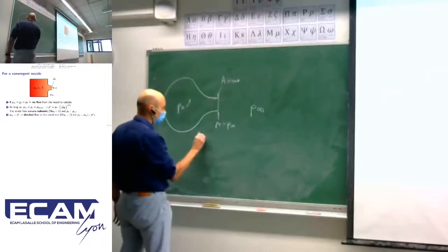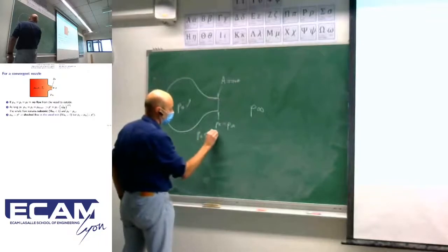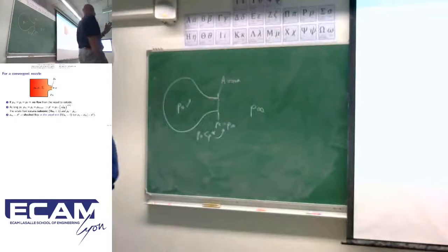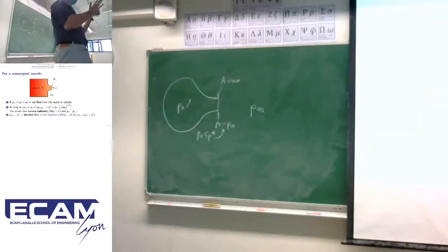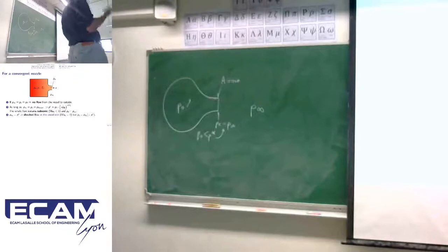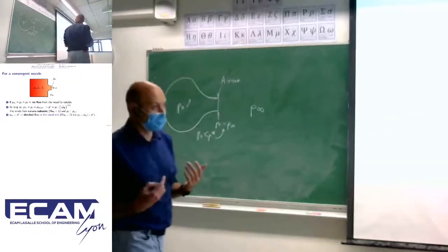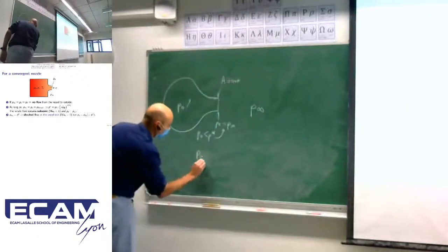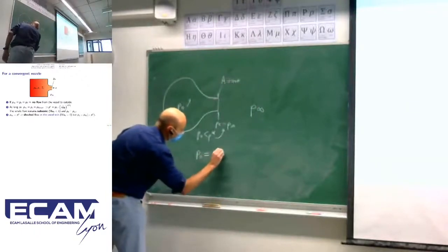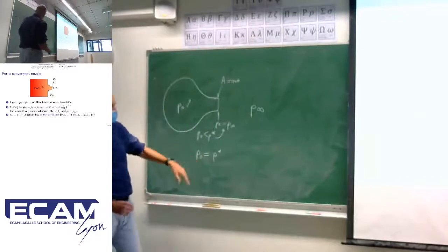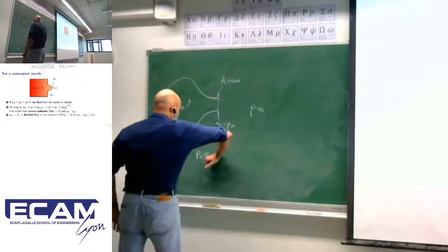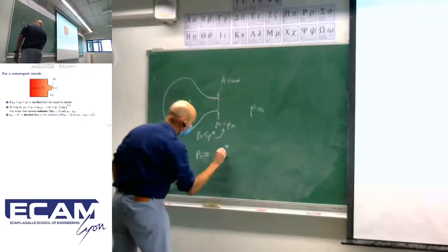So if the stagnation pressure is lower than the critical one, then I have an equilibrium of pressure at the outlet of the system. So it's exactly how it works in usual fluid mechanics. Okay? And I increase again the pressure in order to reach the critical state at the throat. So if I imagine now my P0 is exactly corresponding to the critical one, so my P0 is equal to P critical.